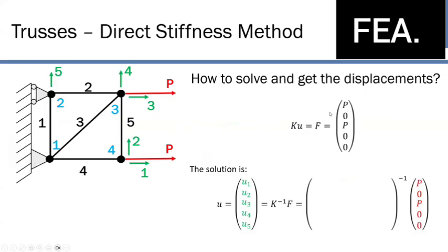And our external loading. So we take this stiffness matrix and we say that Ku, the stiffness matrix times the displacement, equals the force, and that force is going to be equal to the external force. So we can move this to the other side and say that the displacement on its own is just equal to K inverse F, just a simple matrix multiplication to determine what our displacement is. That's basically our ultimate goal. So as an input, we've assigned all of the things I've mentioned. As an output, it's the displacement.